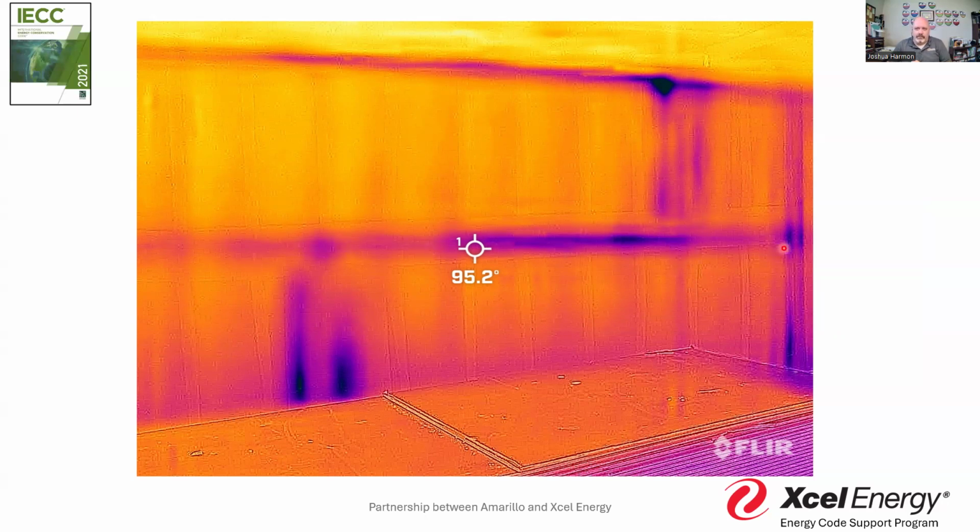We're seeing air loss and heat and cooling passing through the system. And what we're going to end up experiencing over time is condensation, which is always bad for the interior wall assembly. And then we're also going to have equipment not performing effectively, depending on the type of deficiency.